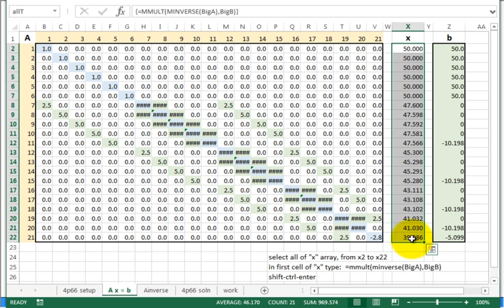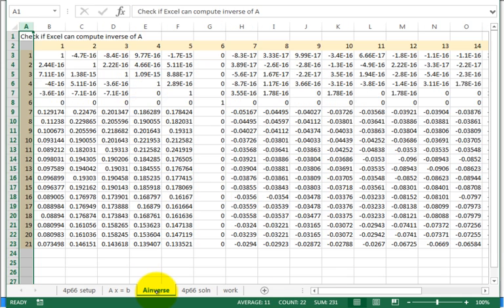So the temperature at node 21, which was way out at the tip, is 39.086 degrees C. And the temperatures of all those nodes are known. So I have a whole thing. The other one is, in debugging, you probably want to check what the A inverse looks like. It's not too pretty, is it? But there's the inverse of that big A matrix. Forget it. Let's press on.